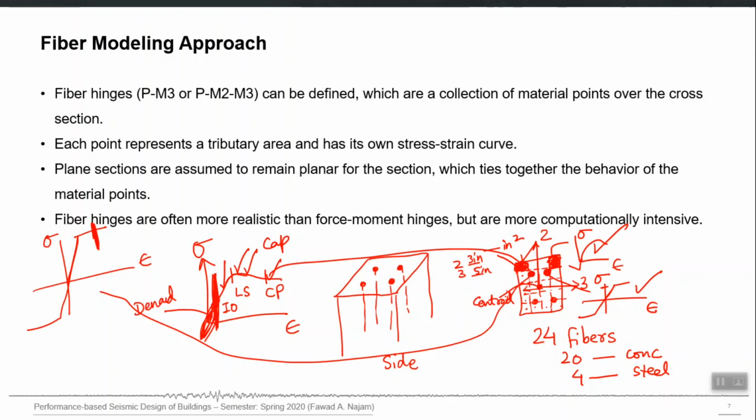So we can call them tensile cracking, compressive crushing, or like that. So the names of performance levels will be indicative of the actual material damage, right? But currently in ETABS it only fixes 3 performance levels, IO, LS, CP, in tension and in compression, right? So we have to use these 3 placeholders, right?